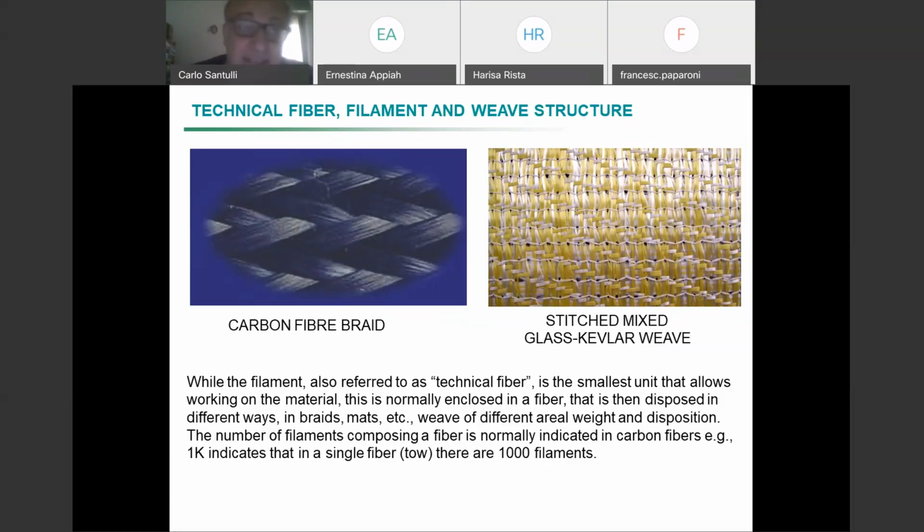Also with natural and synthetic, there are a number of studies, for example, of glass-flax, glass-hemp, because I make fiberglass more sustainable, or I might have a connection with the textile industry and have some flax, some hemp, some weave for free. In practical terms, in some cases I don't feel as confident to use just hemp or flax, so I put together the weave in a hybrid, and so I will be more confident.